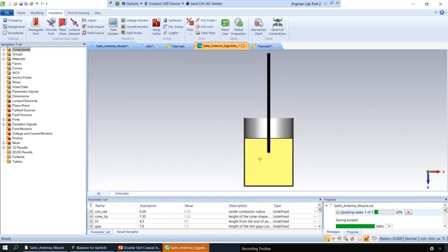So you have all of these S parameters. S parameters in CST are typically displayed in dB, although they don't have to be. Remember, the more negative the number is, so the more negative the dB is, the smaller the number is. Remember, small number is what we want. We want as small of a reflection as possible.